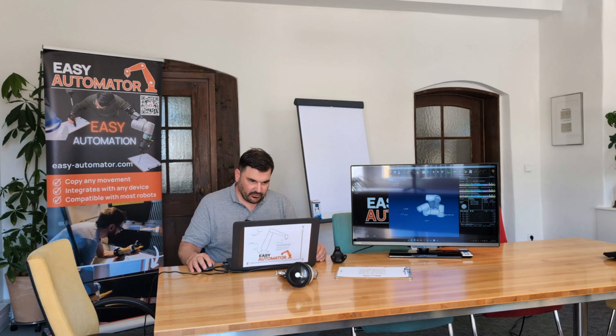This is 0, 0, 200. That means this is my tool. Just wait a second, I will move the robot along a little bit. You can see here, this is the tool. It's 200 millimeters away from the flange, but with the tool definition, the built-in define TCP function, you can define any kind of TCP that you want or that you attached onto your robot.